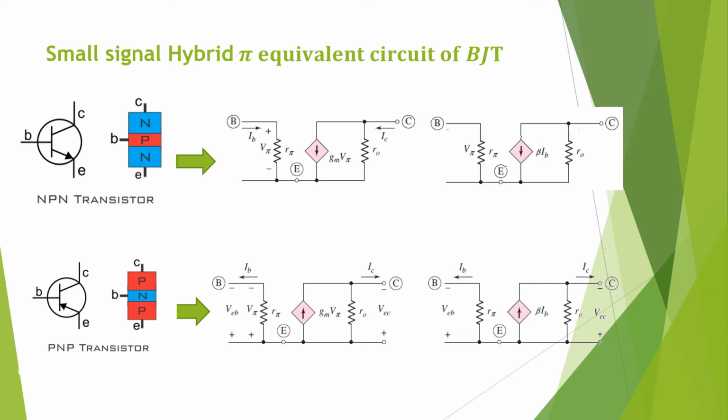In the NPN transistor, the currents flowing through the base as well as the collector are added together, and both flow through the emitter terminal. The emitter arrow direction indicates the holes current flow, that is the conventional current flow. Conventional current depends upon the holes direction, so the direction indicates the holes direction, not the electrons direction.